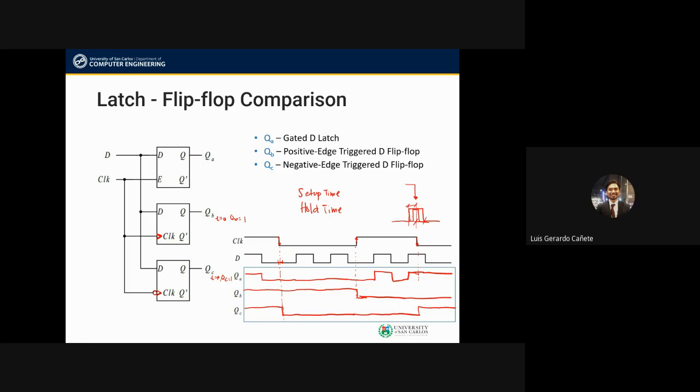Okay, because of the length of the pulse, it's too short, we can't guarantee that it will be sampled. So that's a practical property of a flip-flop. It's not instantaneous, wherein no matter how small the pulse time is, as long as the edge trigger comes, we should be able to sample this value at this very instant. No, it's not like that. There is a minimum time. So there is a minimum length of a pulse that you can sample when we're talking about flip-flops. Okay?